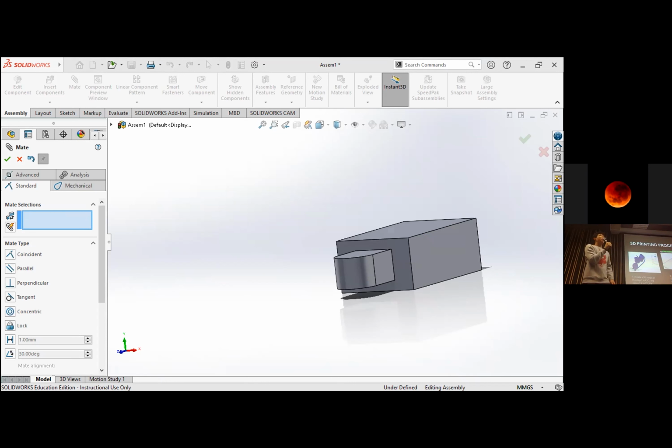We start when we have the file. We have to convert it to an STL because 3D printers can't really use the files that we make because they're all proprietary. Then we get an STL file. We still can't put that in the printer yet because we need to slice it into G-code. So we can use a slicer such as Cura or PrusaSlicer to do it. Then we send the G-code directly to a printer. So that's the process in summary. We will go into more detail next slide.